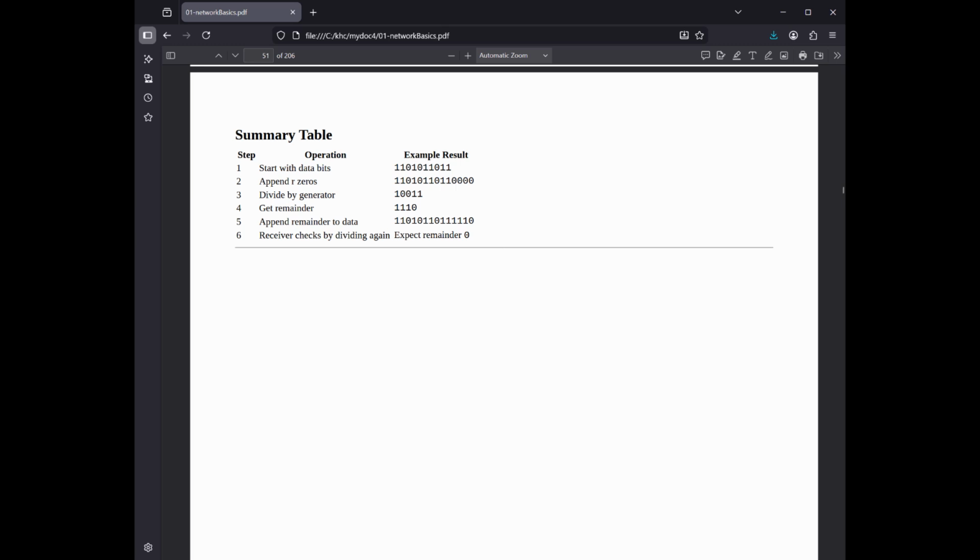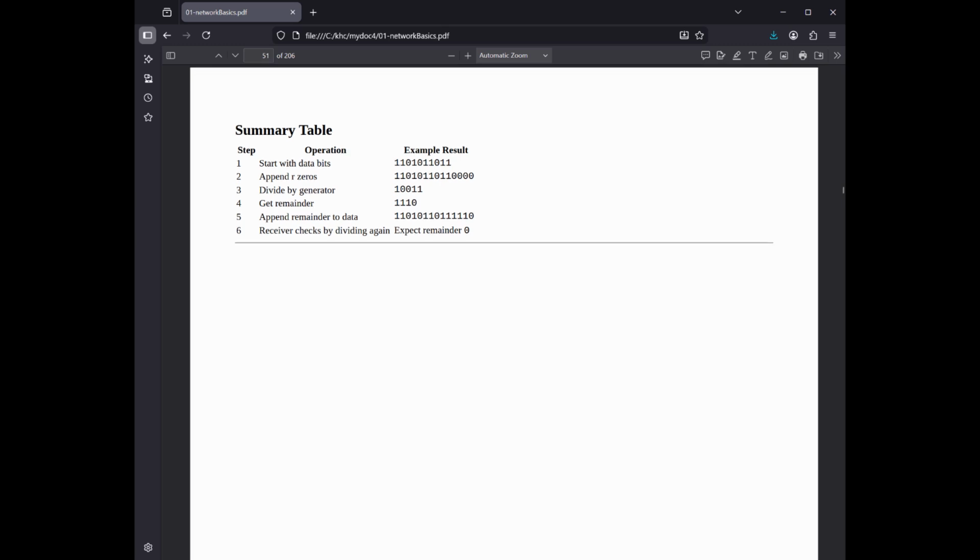In practice, a common way to verify a frame is to run the CRC algorithm over the entire received frame, data plus FCS. If the frame is error-free, the resulting CRC calculation yields a specific, non-zero signature constant, 0x2144DF1C.